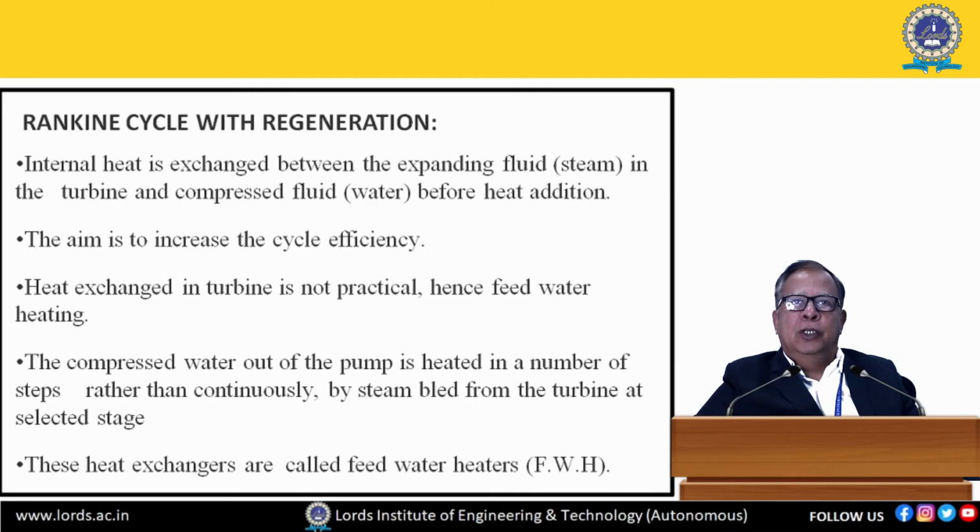Now, heat exchange in the turbine is not practical. Hence, feed water heating is done here. How is it done? The compressed water coming out of the pump is heated in a number of steps rather than continuously by steam bled from the turbine at selected stages. These heat exchangers are called feed water heaters.